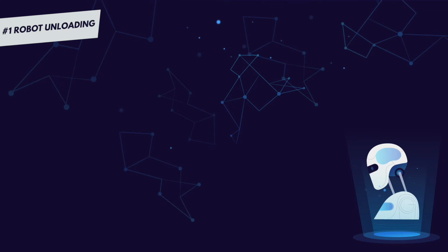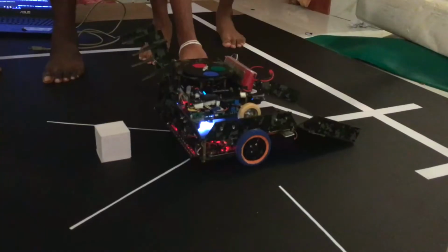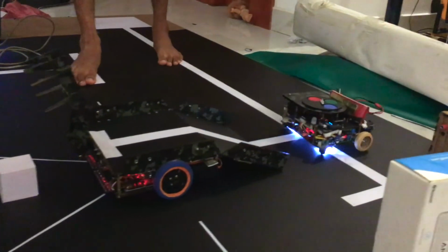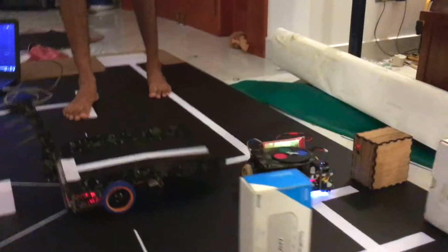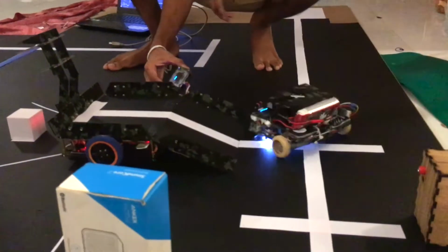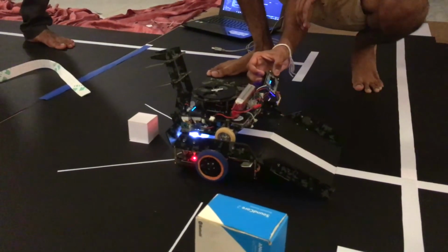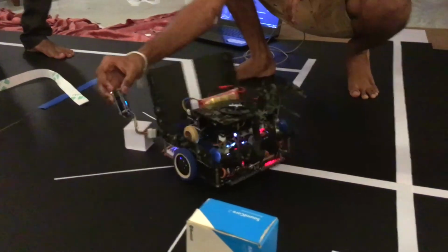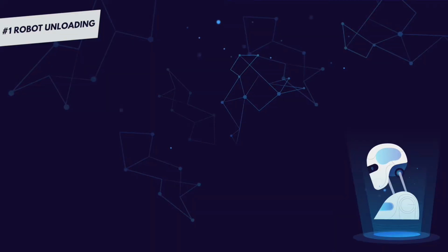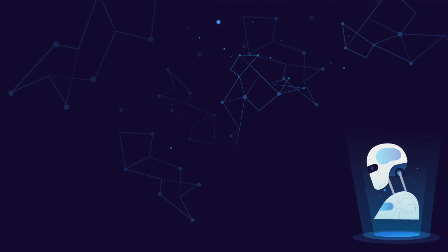We carry our secondary robot on top of our primary robot. When we unload our secondary robot, we use a 3 mm thick acrylic board along with low friction hinges. We used a link mechanism powered by a MG995 servo motor to move the board, and we sharpened the edge of the board to get a smooth delivery to the arena.